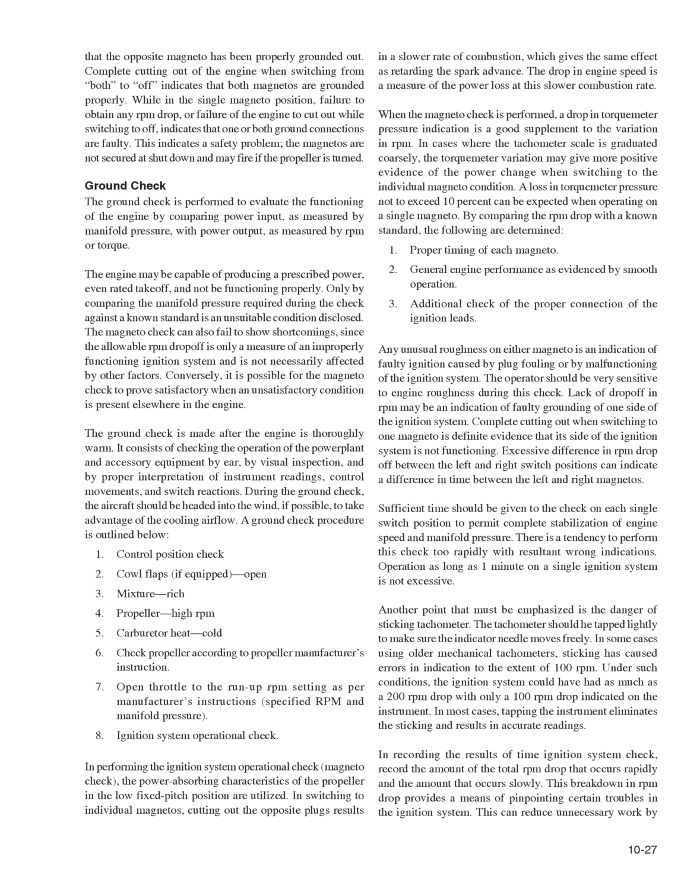Sufficient time should be given to the check on each single switch position to permit complete stabilization of engine speed and manifold pressure. There is a tendency to perform this check too rapidly with resultant wrong indications. Operation as long as 1 minute on a single ignition system is not excessive.